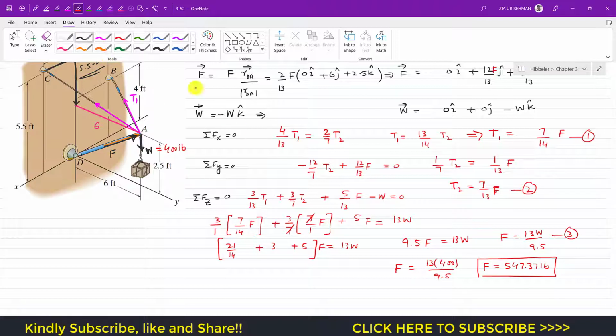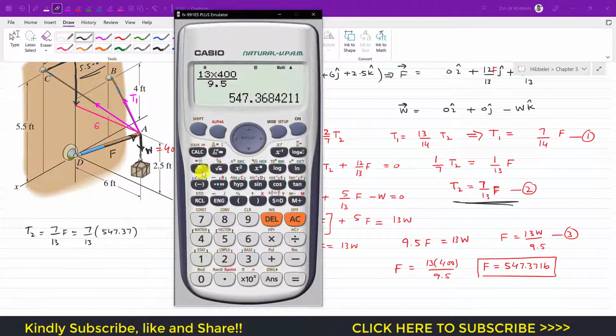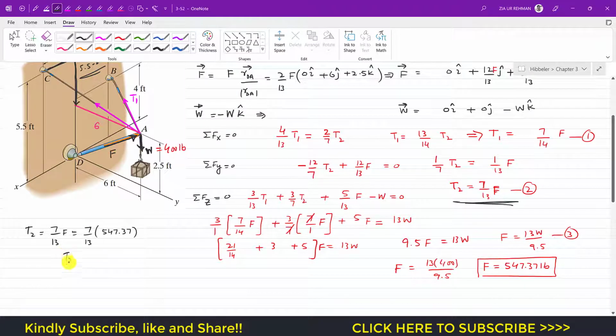Similarly, we can find T2. So T2 is 7 divided by 13 F from that equation 2. So this is 7 divided by 13 multiplied by 547.37. So this gives us 294.74. So T2 is 294.74 pounds.